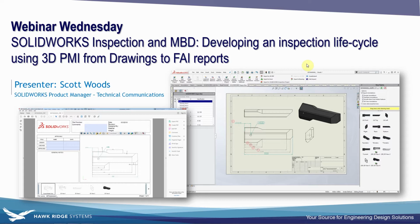So when you have dimensions, notes, annotations, that sort of stuff at the model level, you can reference that data in your 2D drawings. You can reference that data in model-based definitions for PDF outputs, e-drawing outputs. There's also a lot of other uses, such as a STEP 242 file, which we can export from model-based definitions. That file has readable data in the STEP file, so you can share that with vendors, and they could open it up and say, oh, these are the dimensions, this is how things are put together. So there's a lot of benefits to putting that PMI data right in the model level.